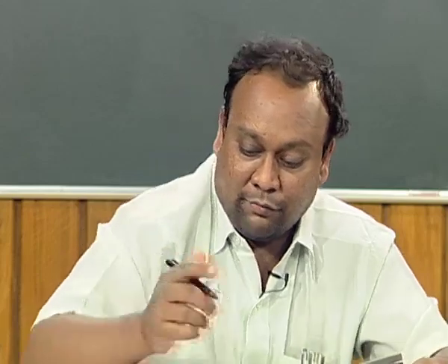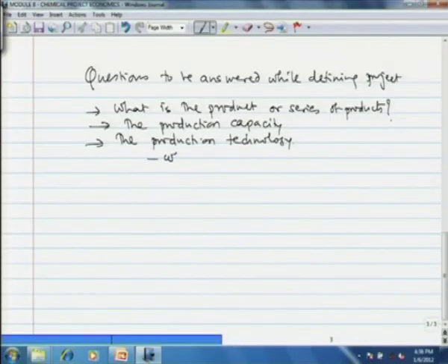The total project cost is typically the fixed capital investment plus working capital. So, the cost of production gives you an idea of the day-to-day expenses. Okay. Now, after you decide technology, you face two more questions. First, what are the returns on the project? What is the raw material that you are going to use, and what is the cost of the product that you produce? That difference gives you the value addition, and is the value addition sufficient to make the investment attractive? That is the question.